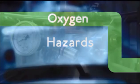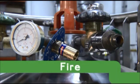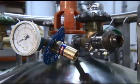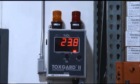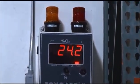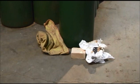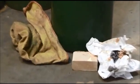The greatest hazard associated with oxygen is fire. As mentioned earlier, while oxygen itself does not burn, an oxygen-enriched atmosphere containing more than 23.5% oxygen can dramatically increase the risk of combustion of other materials and raise the temperature of any fire. Oxygen's ability to support combustion can cause materials that are safe to use in normal air, such as oil and grease, to become hazardous fuels in the oxygen-rich environment.